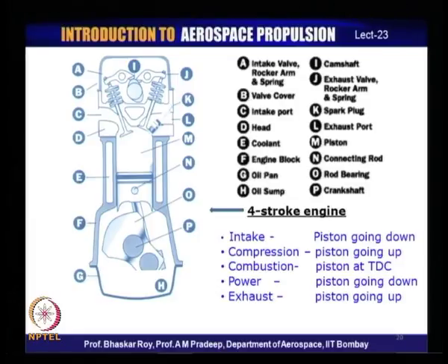And now, what we are looking at is a picture or a diagrammatic sketch of an engine, by virtue of which you can create work or mechanical work, and this engine then moves the crankshaft over here. This is the crankshaft, which creates the motion, rotary motion, and through the shaft power is taken out on a continuous basis for running any working body. In our case, that would be the propeller, which creates the thrust.